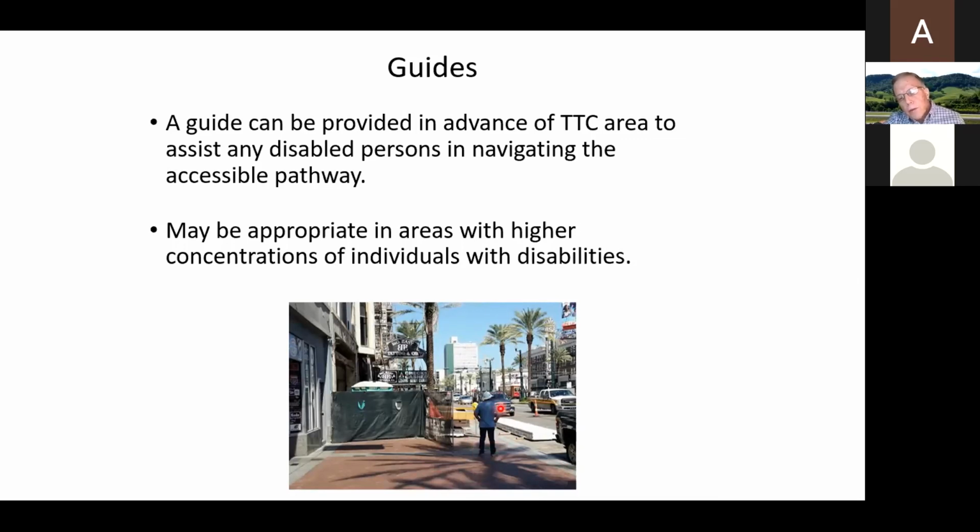And this fellow is supposed to be the guide to keep pedestrians, I guess, from getting into the work area, also to direct them maybe across the street. And that's appropriate. The only criticism I have here is I was here about 10 minutes observing things and taking photographs. And in those 10 minutes, this fellow never turned around to look at pedestrians. Remember, to me, his main focus, if he's a guide, should be on pedestrians and making sure he intercepts or stops or aids pedestrians who need assistance. So the guide needs to be properly trained.